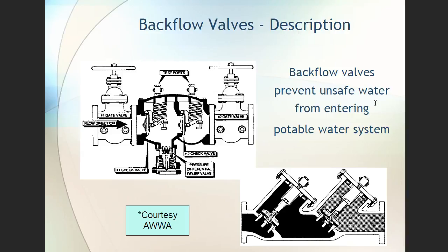Okay, so this is kind of just a cutaway. And what we're looking at here is we have 2 gate valves, one on each side, and then we basically have our backflow valve. I'm sorry, not pressure reducing, our backflow valve. And they're spring loaded. So it's basically the water's allowed through pressure, it's going this direction, to push this open, and it pushes the next chamber open. But if the water tries to go back, those springs slam that thing shut and won't let those waters go through.